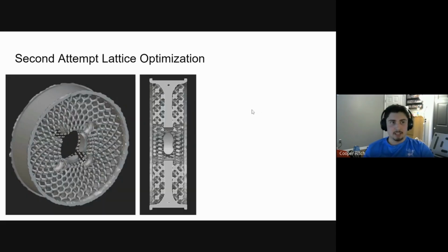And if we look at how we did the lattice, Topology is built to do complex lattice systems because it's all done implicitly, so there's no real meshing. With this lattice, how I showed you earlier and talked about discretization, that's really costly, right? You have to make all those little triangles. And in making a lattice in Topology, it doesn't use the triangles. It just uses equations. And because Topology is powerful for this, we're able to change the thickness in a gradient style. So we use, again, the stress data, and we can drive the thickness based on the data. In areas of lower stress, the struts will be thinner, and in areas of higher stress, the struts will be thicker. And that is filling in our original optimized shape.